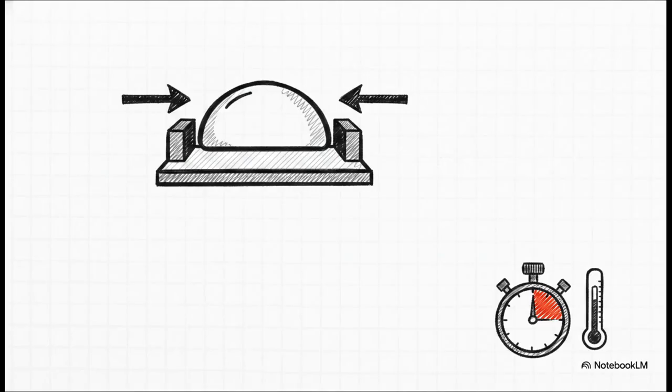But they don't stop there. Alongside the copper pillars, they tightly optimize the reflow thermal profile, dialing in the exact amount of time the metal spends in a liquid state. They also use precise solder mask-defined pads. Think of these as microscopic stencils that physically restrict the liquid metal from bulging sideways.